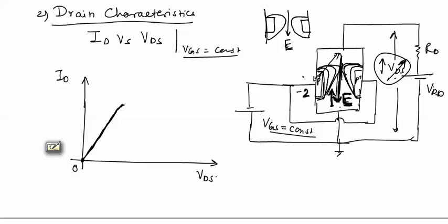So at this point, this voltage is called pinch off voltage VP. At this point, drain current ID saturates. At this point, both the depletion layers touch each other, and this voltage is called VP. Remember that this voltage VP is different from the voltage that was seen earlier.